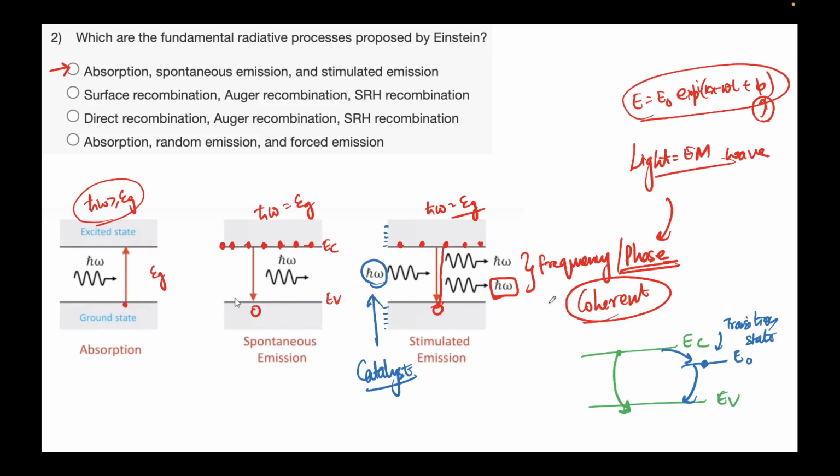I'm saying that usually there is a transition state involved, which increases the probability of going through. So it's not staying here. It's in fact a single process. I'm just drawing it here for illustrative purposes. This incoming photon helps this transition for an electron to drop from EC to EV. That's all this incoming photon is doing. That's why it survives. It's not getting consumed here.